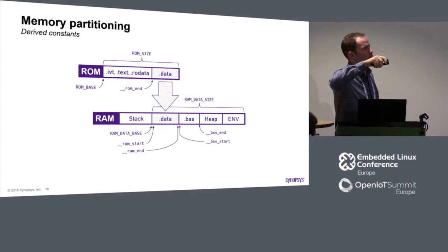So that's the place where we start copying data. And here you see RAM start is the location where we're going to copy. So basically we copy in a cycle everything from here to here. And so we know the size as well. We may calculate it even during compilation, and so that is very simple. And we know as well the location of BSS, so we may easily zero it later on.